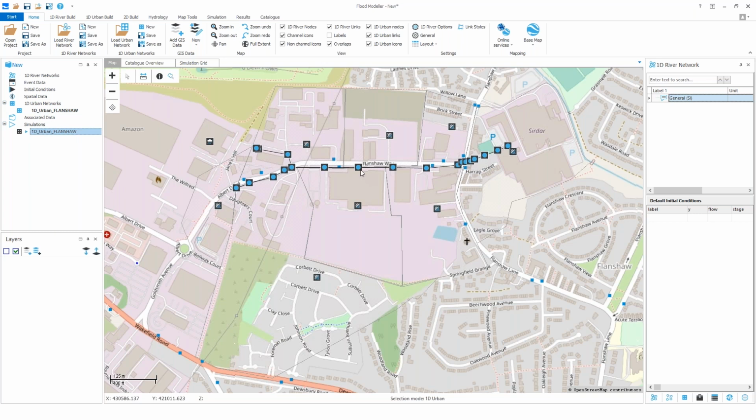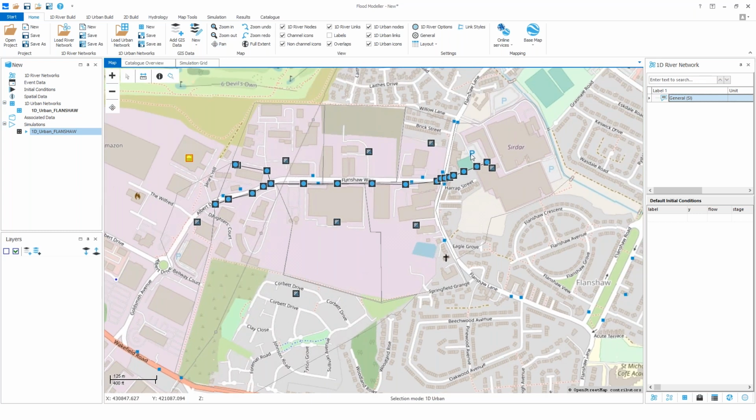So you can see that the network is made up of a series of junction nodes, conduit links, subcatchments providing inflows to the model, and a rain gauge that provides rainfall inputs to the subcatchments. However, hopefully you can tell at the downstream end, the network is incomplete and so needs editing. We want the network to end at the river channel that's shown here on the background mapping. So we're just going to add a few units just to complete the network there.